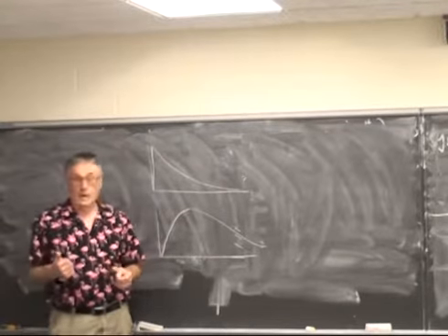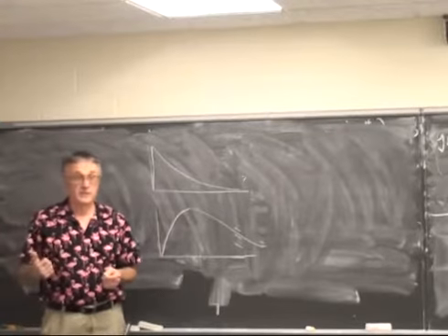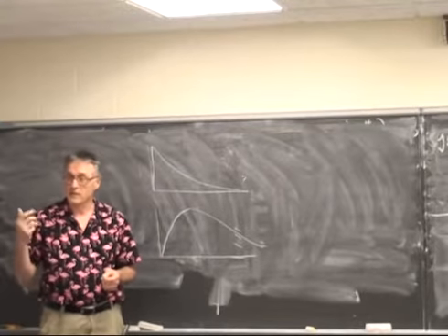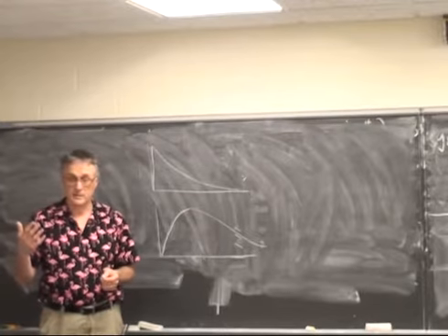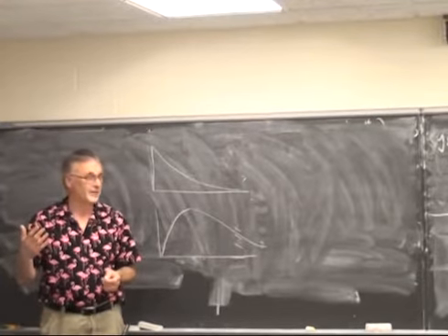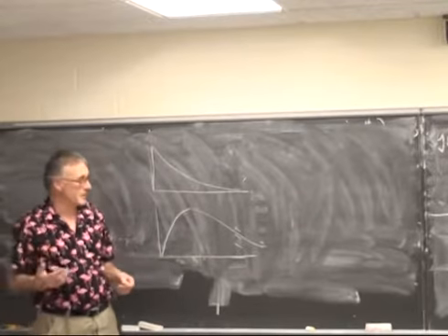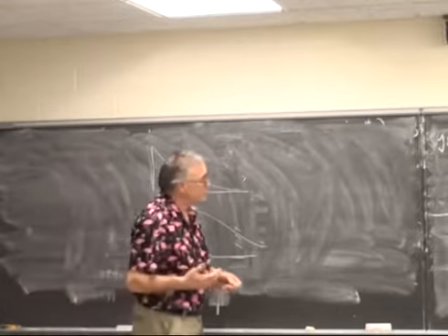The work required in terms of direct digital synthesis is fairly high. That's 5 harmonics, requires 5 DDS units. Not a big problem on the FPGA. You could put 150, probably 1,000 DDS units on the FPGA.